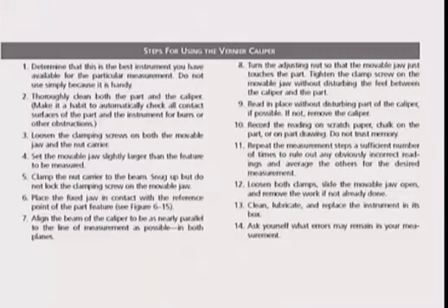Steps for using the vernier caliper. Determine that this is the best instrument you have available for the particular measurement. Do not use it simply because it's handy. This is a common error. People like to use them because it's handy, but often it doesn't have the resolution. You need to be using the correct gauge for the job.